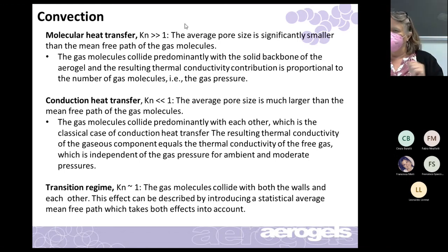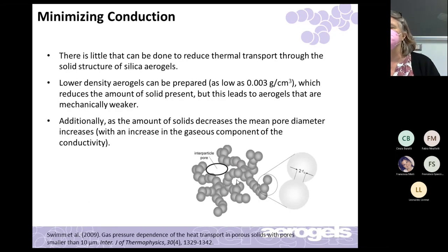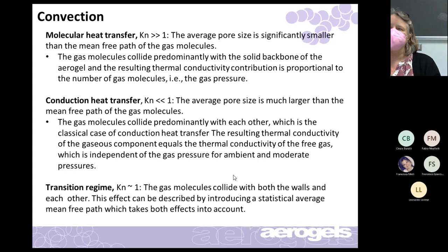But it's complicated because there's also the solid phase too. So the Knudsen number is what made the difference between air and hydrogen. Sort of, yes. So if you have a Knudsen number lower than 1, your hydrogen is like air for the purposes of convection.